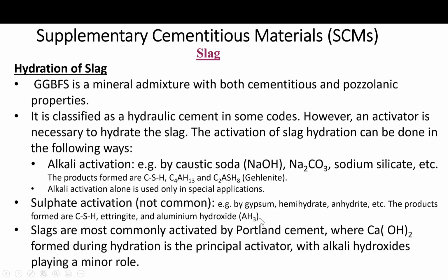Care must be exercised when using any of these activators because of their potential adverse effects on the concrete, if they are used in concrete, which I said they are not. Slags are most commonly activated by Portland cement, where calcium hydroxide formed during hydration is the principal activator, with alkali hydroxides playing a minor role, if at all.